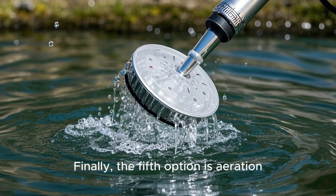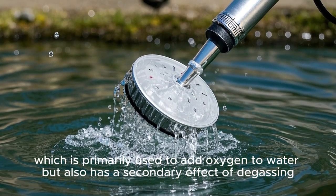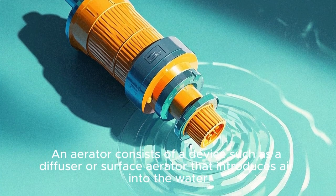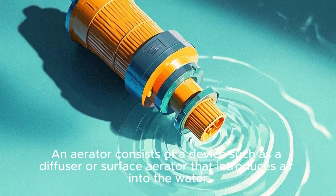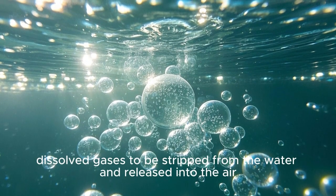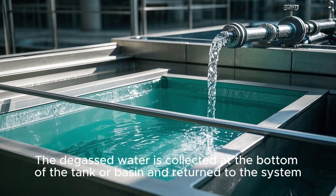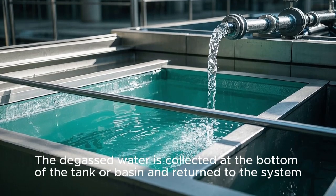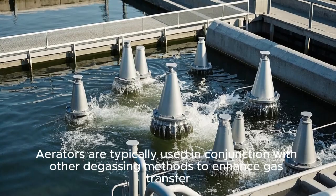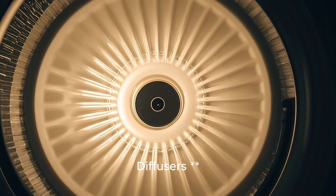Finally, the fifth option is aeration, which is primarily used to add oxygen to water but also has a secondary effect of degassing. An aerator consists of a device such as a diffuser or surface aerator that introduces air into the water. The air bubbles provide a large surface area for gas exchange and allow dissolved gases to be stripped from the water and released into the air. The degassed water is collected at the bottom of the tank or basin and returned to the system. Aerators are typically used in conjunction with other degassing methods to enhance gas transfer. There are many types of aerators available, including diffusers.